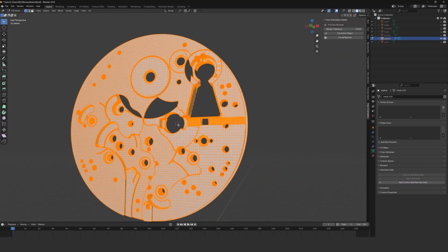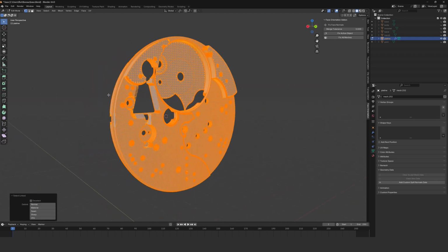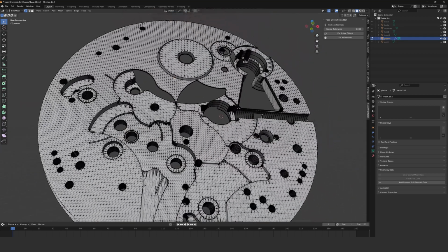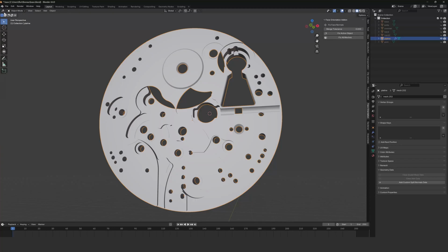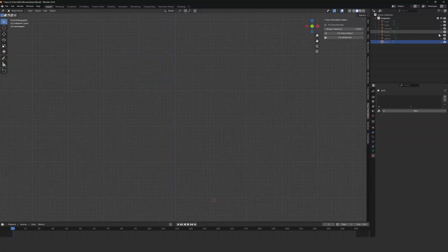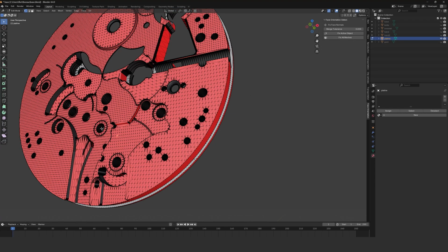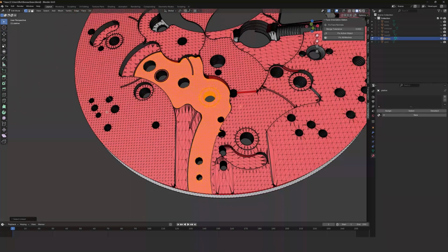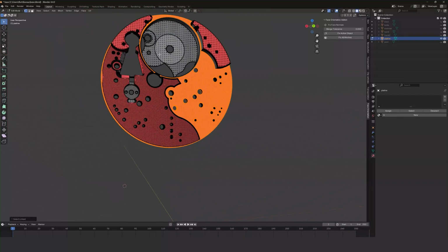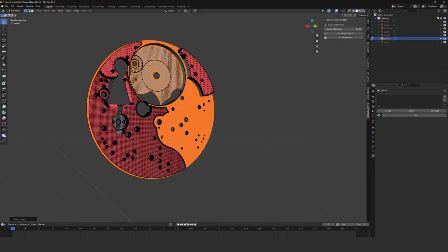However, once in Edit mode, it becomes impossible to select specific faces. Now it's a single, unified, manifold object, whereas before, it was possible to select distinct face groups, useful for assigning different materials or textures to specific areas. That's why this alternative method isn't ideal. And that's exactly why I created the Face Orientation add-on, which solves this problem.